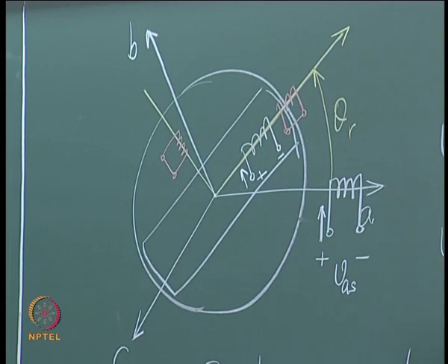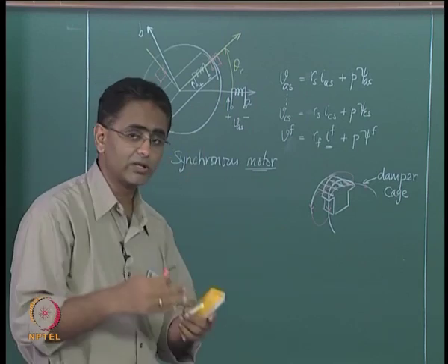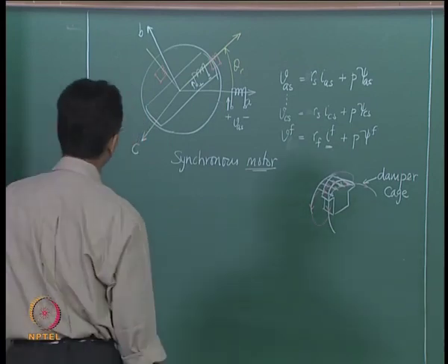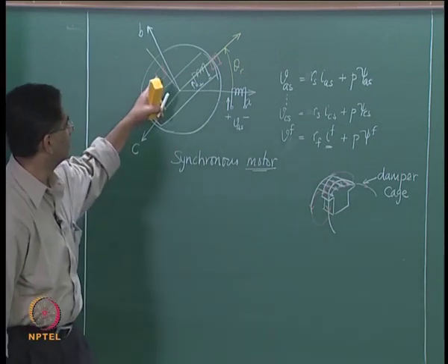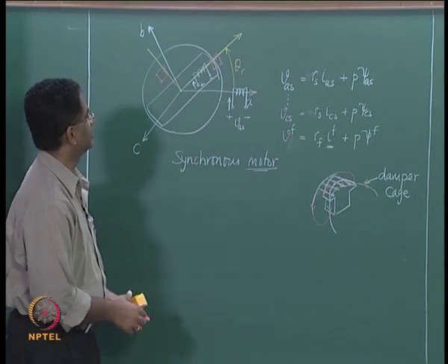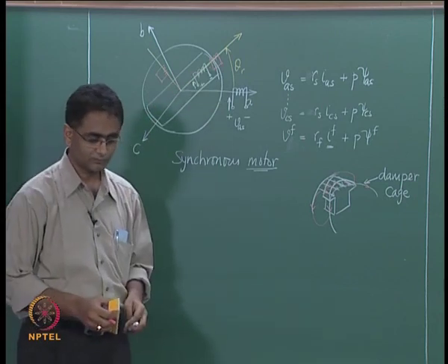Therefore there is at least one coil on the Q axis and one coil on the D axis. Now if one wants more accurate results of simulation, perhaps one needs to consider more shorted representations on the D axis and on the Q axis, but in general people have found that sufficient accuracy of simulation is obtained with one coil on the D and Q axis.